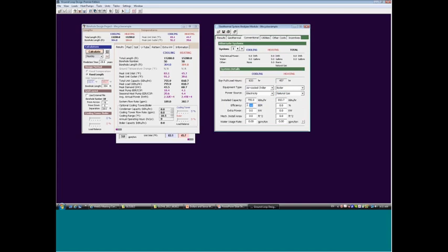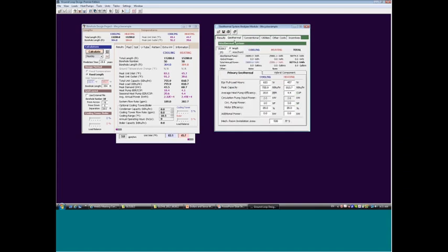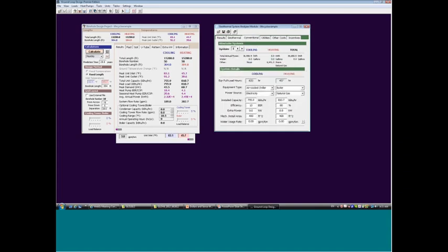So maybe the average efficiency of the air-cooled chiller is 13. Maybe the boiler is, I don't know, 80%, for example. Sort of nothing special. We could put extra power, but I'm not going to worry about that. We can put the mechanical installation area. Let's say this conventional equipment has a larger mechanical room footprint. Let's say it's a total of 800 square feet for the conventional mechanical room. So we put 500 feet in for the geothermal one and 800 for the conventional, 400 plus 400, for example.